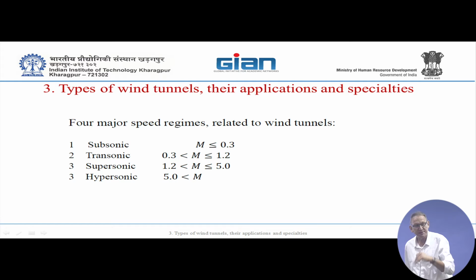If somebody comes with 4.9, nothing happens. But one of the definitions of hypersonic is the Mach number at which you have to heat the flow in order not to get liquid when you accelerate or expand to high Mach, to Mach 5. The moment you have to heat your flow, that's the Mach number that is hypersonic. That's one of the definitions.